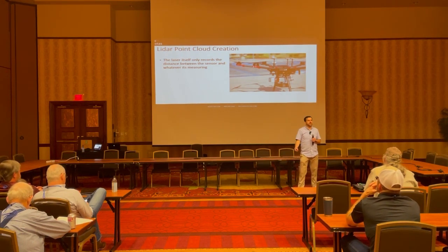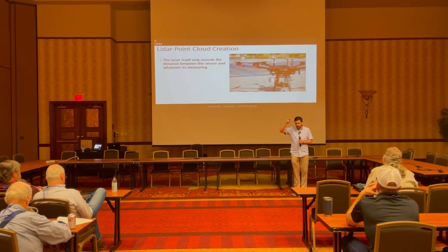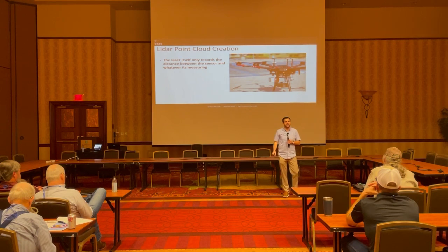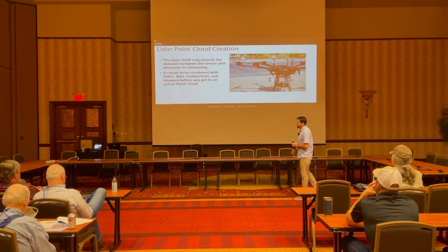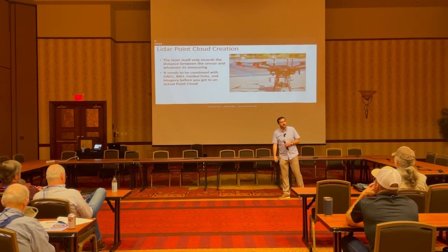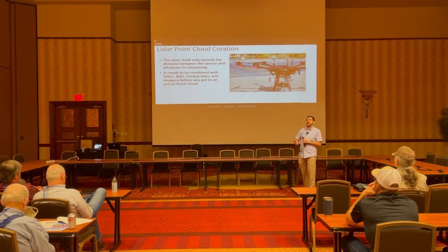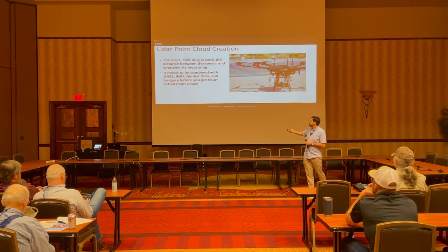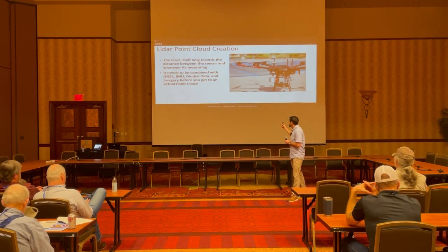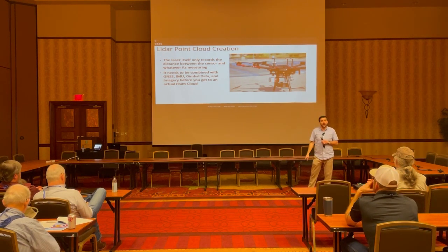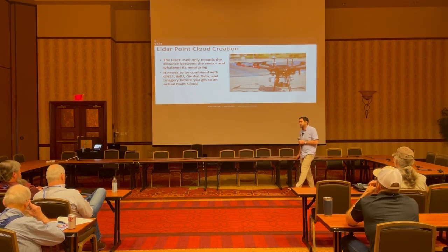See, the way that a laser scanner works is the LiDAR sensor itself only records the distance from the laser itself to the ground. It doesn't know where it is, it doesn't know what angle it's pointing at, it doesn't know any of that sort of thing. So in order to actually create a point cloud out of LiDAR data, you need to process the raw laser scanner data with information from the GPS or GNSS system, the IMU, an inertial measurement unit, any gimbal data, and often the imagery to colorize that point cloud before you can do anything else.